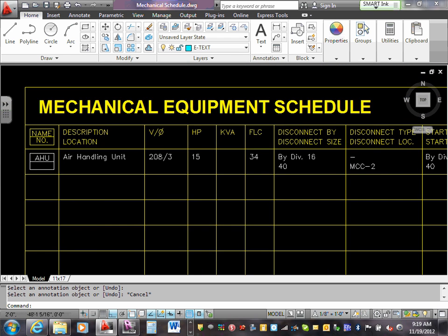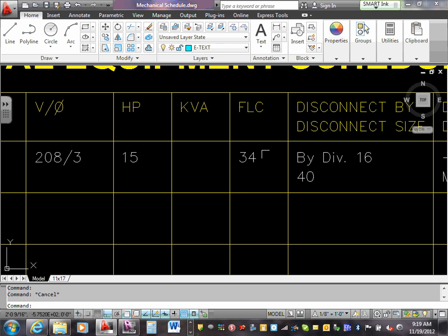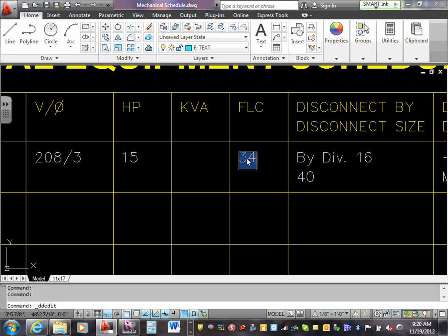Yes, absolutely. The second one, the full load amps. Jeff, what's the full load amps from NEC for this one? For a 15 horsepower, 2.8? Anybody can be my friend here. Tell me what's the 15 horsepower full load amp? Come on. From the NEC code book. My friends. Oops. 46.2. Thank you. 46.2.